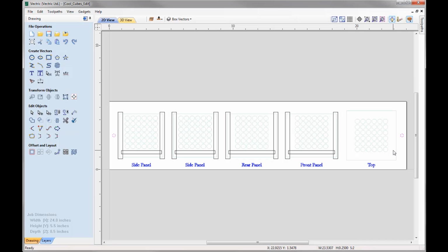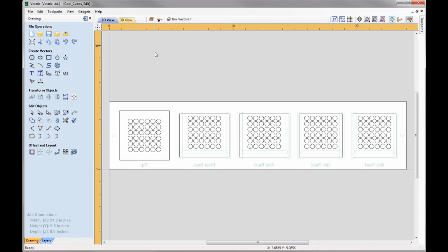We're going to cut all the way through the material, and we're going to cut into the spoil board, where we'll then take our material off as we've finished with the top side, and then we're going to put the dowels into the spoil board, and then when we flip our material over, we're going to align it back in X and Y into the position, secure the part in place, where we'll then go and run the toolpaths for the bottom side. I'll look at machining all of the decorative elements, followed by profile cutouts to cut all of these panels out. So let's go and run these toolpaths.